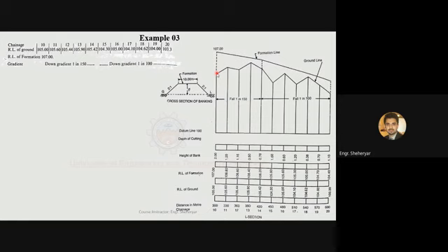And if the value comes to be negative, then what does it mean? That means it's cutting, not filling. Yes, cutting, because it will mean that the ground level is higher than the formation level, and you need to cut the ground material so that it can be in level with the formation line.